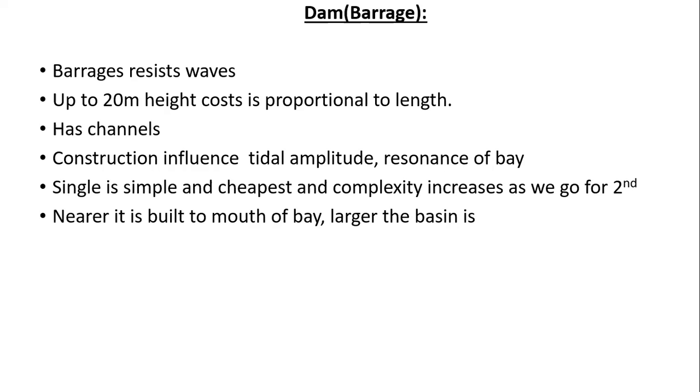Okay, and tidal barrages require sites where there is a sufficiently high tidal range. The minimum useful range is around 3 meters. The best sites to build a dam or barrier are a bay or estuary. But water can also be impounded behind reservoirs built between two points on the same shoreline.